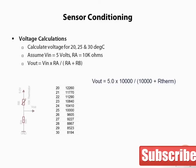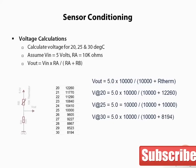Substituting, Vout equals 5 volts times 10,000 ohms divided by 10,000 ohms plus our thermistor. So for V at 20, it's 5 times 10,000 divided by 10,000 plus 12,260. And so on for V25 and also for V30. So solving, we get V at 20 degrees C equals 2.246 volts, V at 25 degrees C equals 2.5 volts, and V at 30 degrees C equals 2.748 volts.